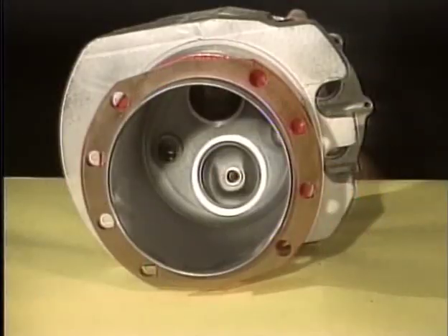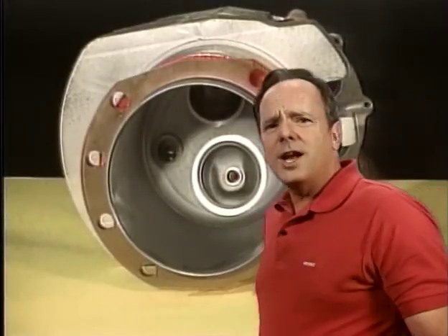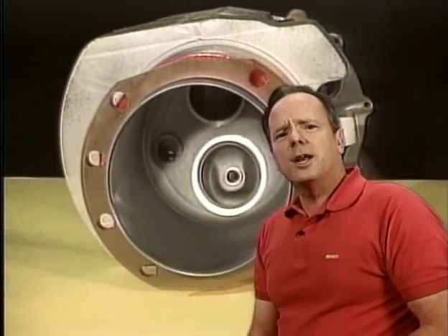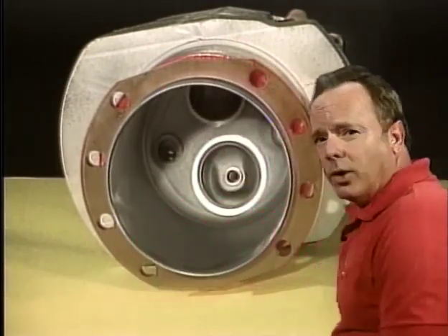All right, let's assume that you're operating a cold engine. If the oil pressure of the cold engine is higher than at normal operating temperatures, what does that mean? Well, what they want you to know is it's normal for an engine to have high oil pressure when it's cold. That means the engine's lubrication system is probably operating normally. Now, of course, as a mechanic, when you change the oil in an engine, you want to examine the oil, check the oil screen to make sure that there are no metal particles in the oil screen.